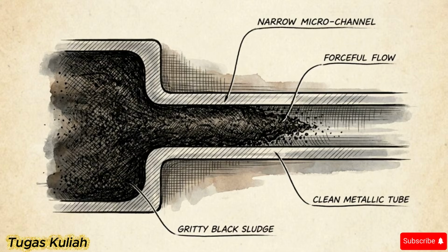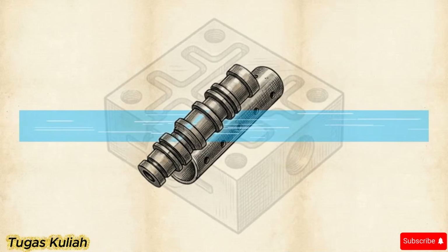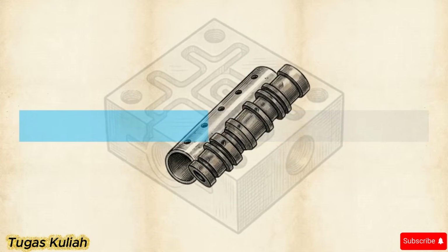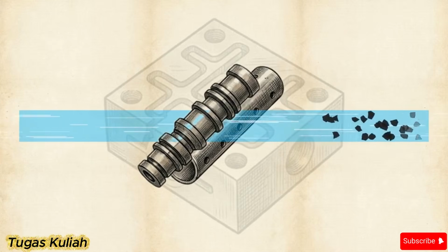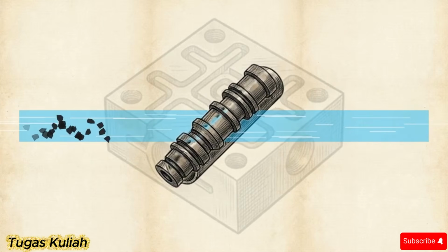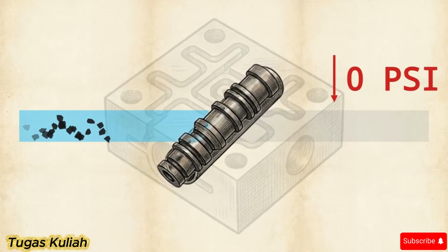The transmission pumps this particulate-heavy sludge directly into the tight tolerances of the valve body's microchannels. This cross-section shows a shift solenoid attempting to slide open to regulate hydraulic pressure. The abrasive particulates wedge between the moving piston and the cylinder wall, halting its movement entirely. Because the seized solenoid cannot route the fluid correctly, there is an immediate pressure drop in the surrounding hydraulic channel.